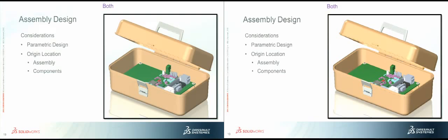The other issue is, where does the assembly go, or the assembly origin go, and where do all the planes go? And we'd like to make sure that all the parts are lined up the same way. As your assemblies get bigger, sometimes that's really nice to have all the front planes parallel to one another, right planes parallel, and top planes parallel. And we'll build the parts that way. So with that, we're going to start building.